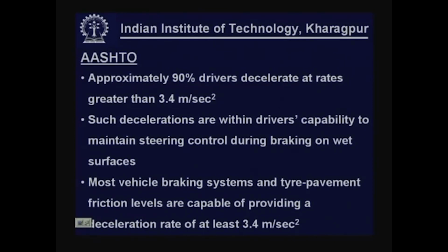Also, it is found that such decelerations are within driver's capability to maintain steering control during braking on wet surfaces, because wet surface is critical as compared to a dry surface. So, even on wet surface, drivers can very well keep control on the movement of vehicle with deceleration 3.4 meter per second square.